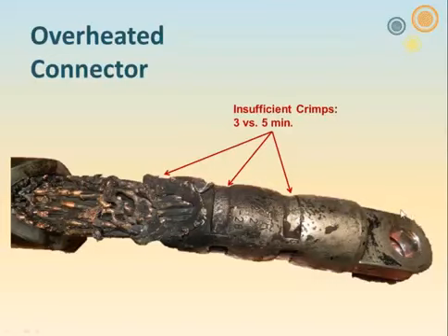So what you're looking at here is 1/2 the diameter of the cable conductor. Then we have the cable insulation. Here we have the accessory jacket, and this particular accessory is either a 600 amp T-body or a disconnectable splice. And we know that because of, well, you'll see in a moment, the cable adapter. This is the conductive insert of the T-body, and this is the insulation. Here, this section here is the cable adapter insulation and the cable adapter stress cone.